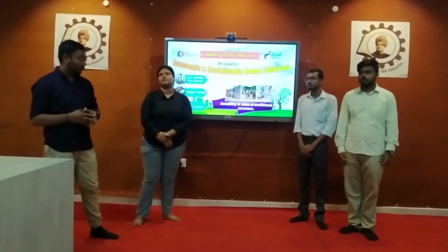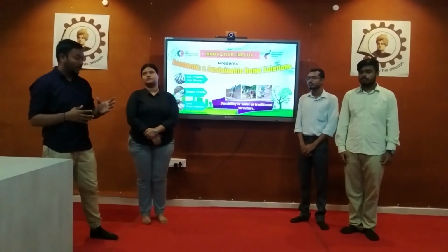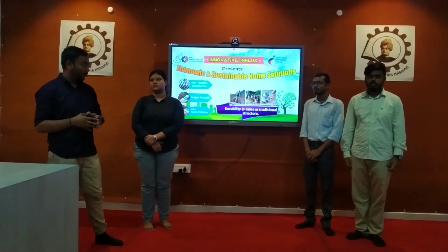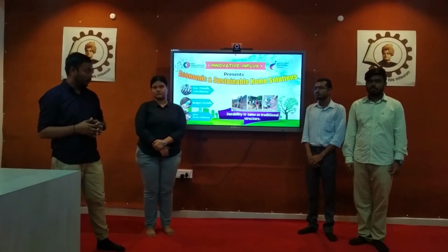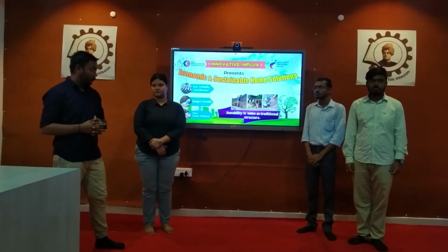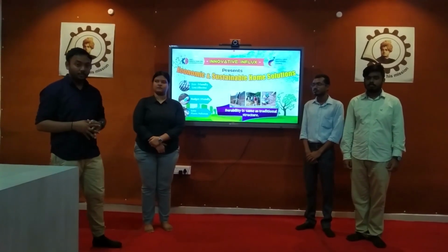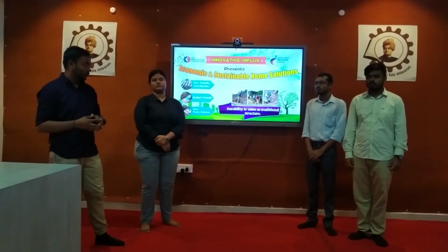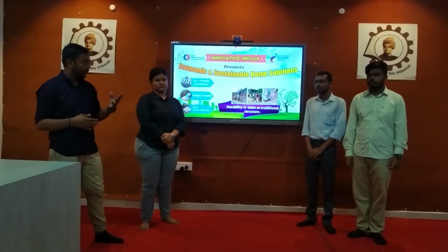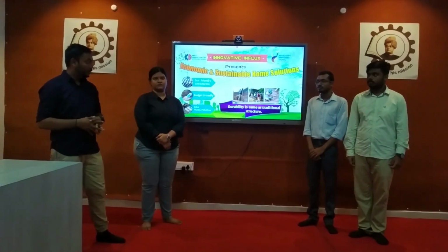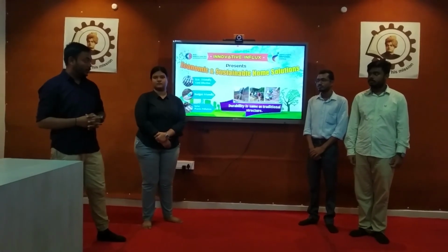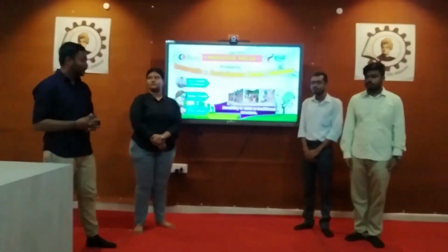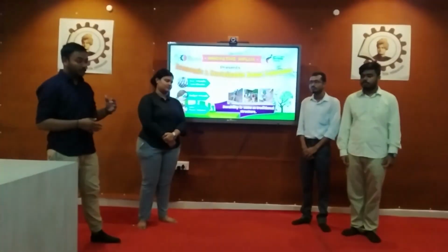Then we have to treat the bamboo chemically, otherwise we cannot use it properly in this building. In order to chemically treat the bamboo, we have to use boric acid and water. That is how we will treat the bamboo. And if we use the treated bamboo in this building, it will give almost 15 years of lifespan to this building. So that is how we want to create this project and this model. Obviously it also has drawbacks. I mean, advantages and disadvantages are there. So my team member Tufan will describe the advantages and disadvantages of constructing this building.